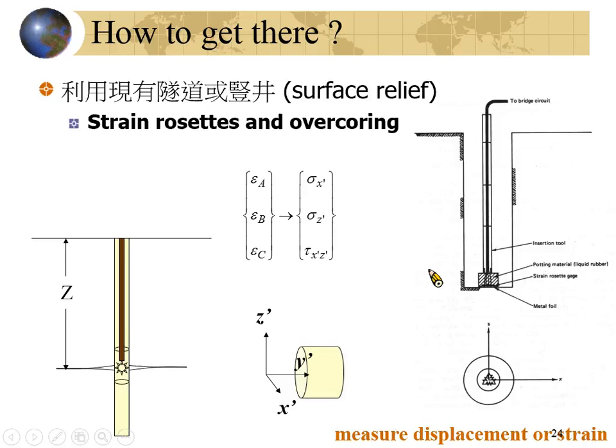And we try to make the strain gauge attach tightly on the polished surface. You don't really have the chance to do the uniaxial compression test for rocks. Usually you need to attach the strain gauge on the rock surface tightly because you want your rock deformation to be identical to the strain gauge.